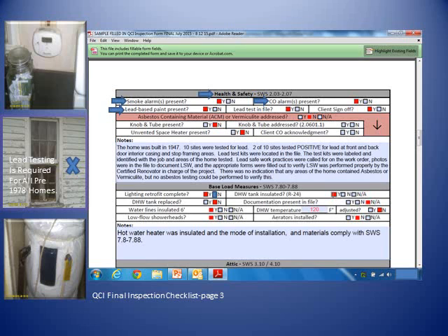You also need to determine if lead-based paint is present, and in this particular case, lead-based paint is indeed present. And if so, verify that lead paint testing was performed. Is there a lead test kit in the file? Was there a client sign-off to verify that they had received the proper education and received the Renovate Right pamphlet?